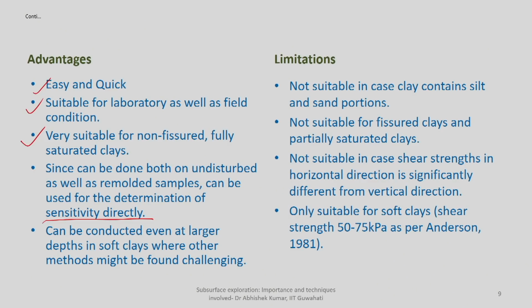It can be conducted even at larger depth, whereas with other methods you have to collect the soil sample and bring it to the laboratory for conducting the test. That may be challenging, but this test you can even conduct at larger depth. Again, depending upon the depth, the force applied or the torque application range will also increase, so we have to think and get ready with that kind of arrangement. If you go deeper and deeper, the torque applied may not be possible manually. You can go for some mechanical arrangement also if possible.